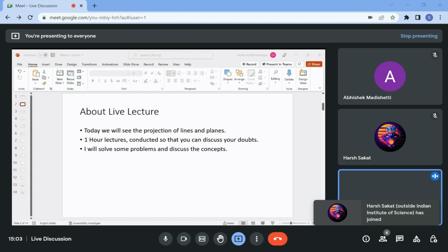In case it is not parallel to VP, the point B will be somewhere here. So the angle that we see is more than 30, whereas since my B point is still here, the actual angle, the true angle with HP has still not changed. So the circle is the locus of all points B when line AB makes a true angle of 30 degrees with HP, or any true angle which is a constant with respect to HP.